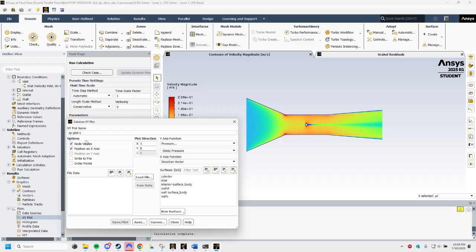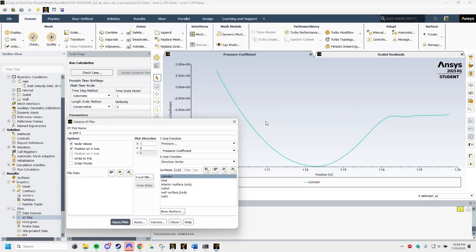And this you need to write to a file because Fluent uses the incorrect velocity, the velocity of the inlet and not the velocity in the test section. But in general, pressure coefficient looks something like that.